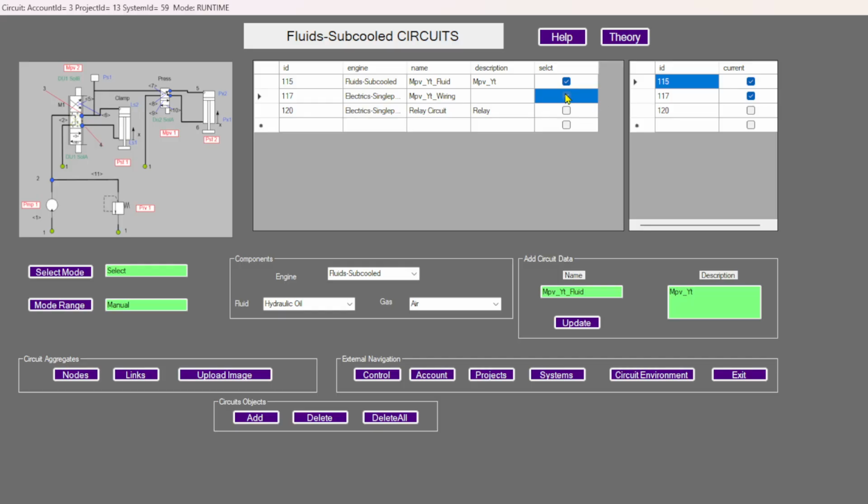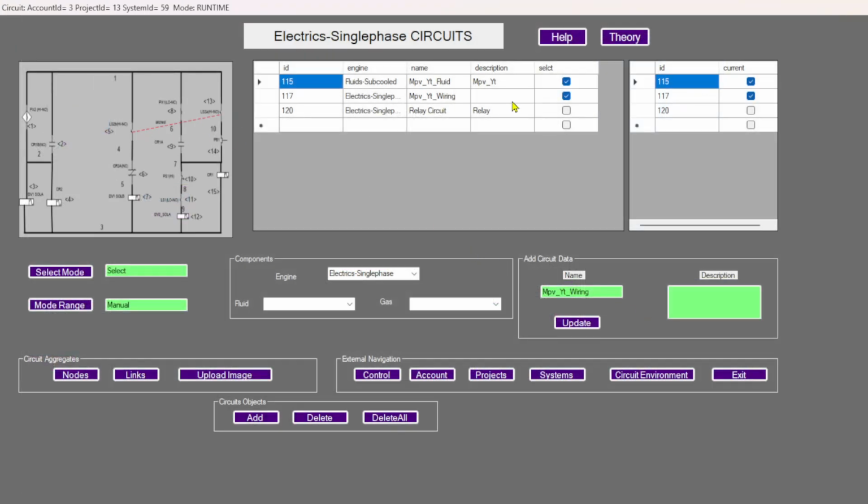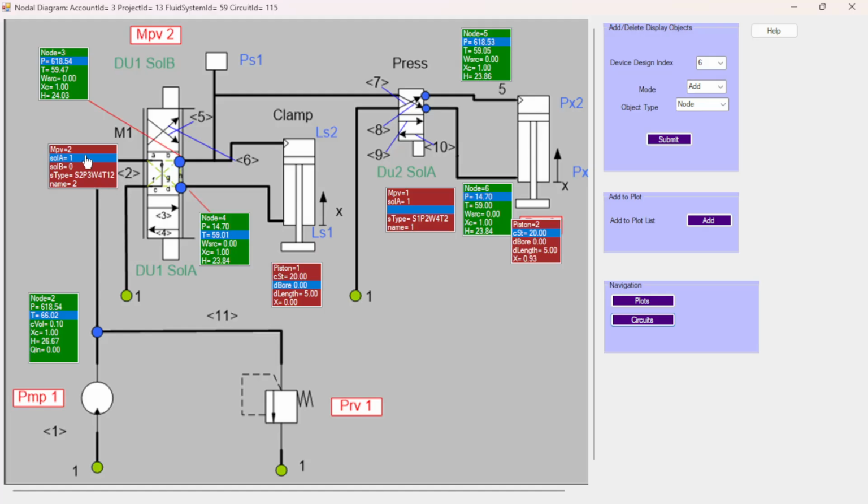as I say, we can see that everything is back in the static state. If I close the switch, okay, then the relay becomes energized, and then solenoid A becomes energized, solenoid B is de-energized. And if we go back, we can see it here. So the solenoids have changed state. All this is being computed from the wiring diagrams and overrides the solenoid positions in the thermohydraulic circuit.